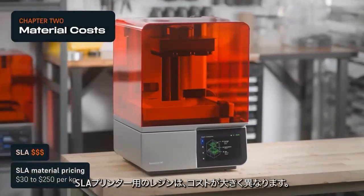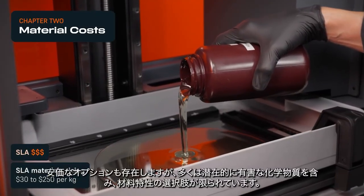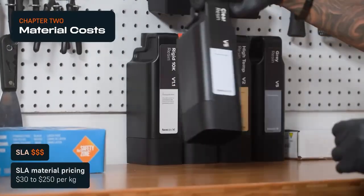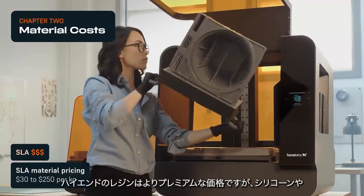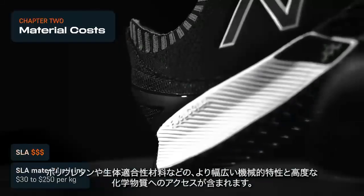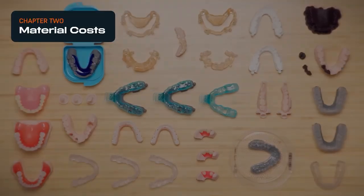Resin for SLA printers varies widely in cost. Low-cost options exist, but often contain potentially harmful chemicals and have limited options for material properties. Higher-end resins carry a more premium price tag, but include a wider range of mechanical properties and access to advanced chemistries like silicone and polyurethane and biocompatible materials.